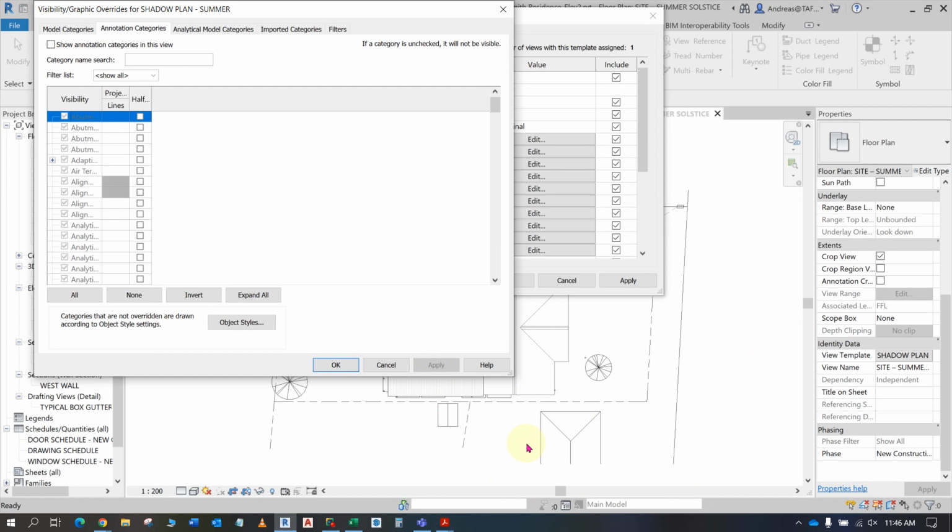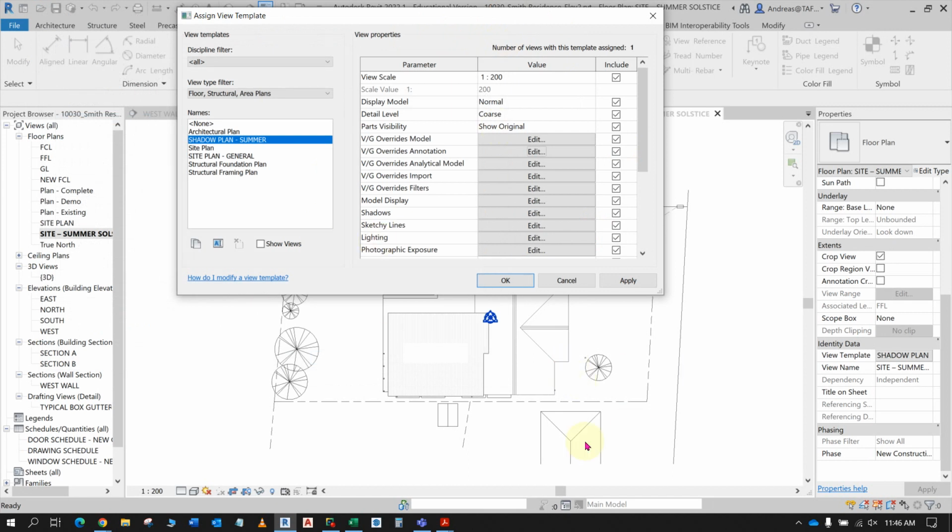All right. Because we copied it with detailing, all the text came across and the hatching and things like that. But at the end of the day, we didn't want the text. So we could have gone through and deleted each text, but the method we chose here is to just turn it off. You got that? Yeah, it's just the second button. So if I go OK there, it's that button there, and we'll just untick the top left one there with the bright light on it. Yeah. All right, so that's working.